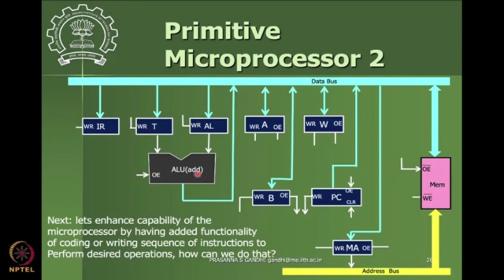So now what we need to introduce here is, as you notice, we have introduced a register called the PC register. This is like a program counter register. This will keep track of which instruction you are running at present. You have some sequence of instructions that are typically written as a program. That's what you write when you write a program, right? You write the first command line, second command line, like that, and one after the other they get executed. So this program counter register is a special register which will keep track of that count.